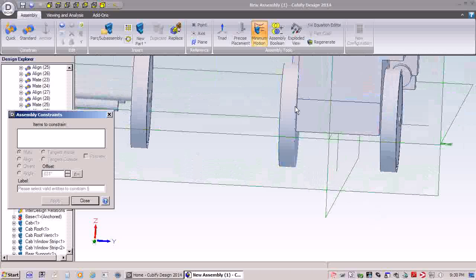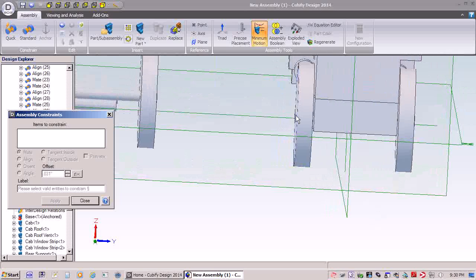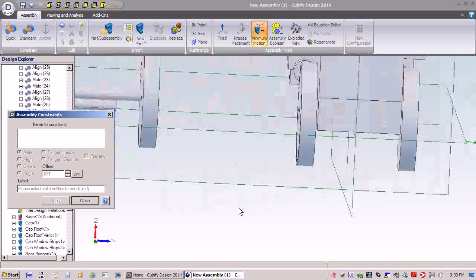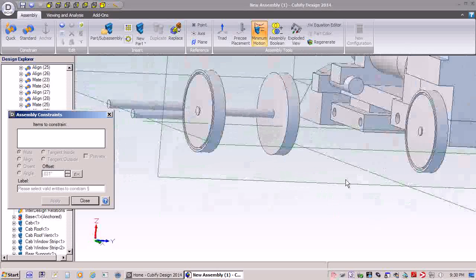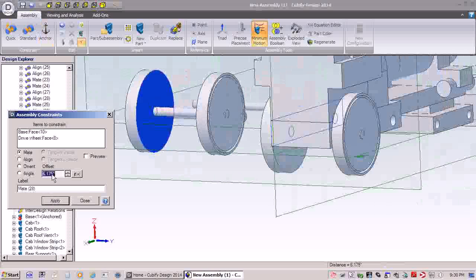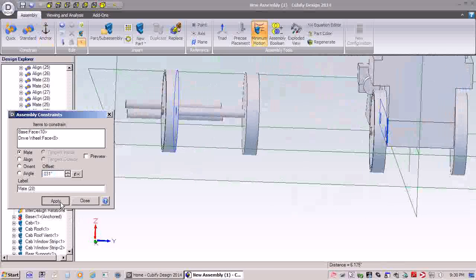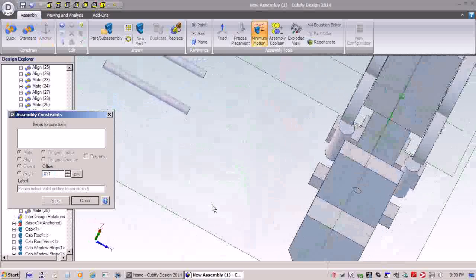So I've got a 1/32 space in there and in there. I got the 1/32 offset from the hub axle. And so I'll just do that one more time with the other wheels that I've got assembled. Do the mate, do the 1/32. Again, it should be positive. And we're good on that set.